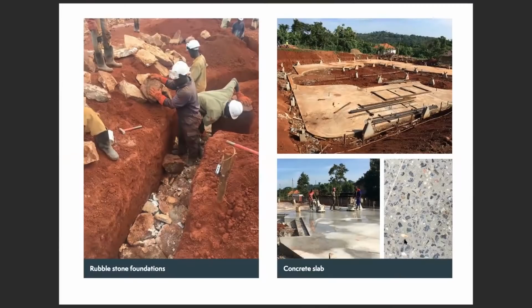The foundation, there are different foundation systems that you could use with this, but we would prefer a flexible kind of foundation system with rubble stone. Rubble is very good because it doesn't allow moisture to rise, but it's also a natural spring. So if there's any settlement, it is able to contain the settlement without causing damage. And it's also very good here we are not in an earthquake zone, but when building in an earthquake zone, loose rubble is quite good for that part, because it's really a natural spring to build on.